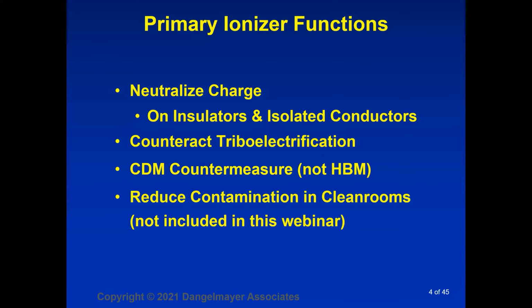Ionizers will also counteract triboelectrification. The ability to generate charge on materials in an ionized environment is lower than it would be if there was no ionization present. Remember that ionization is a CDM countermeasure. It's not for HBM. We don't use ionizers to neutralize the charge on people. It just wouldn't work. In any case, remember that it's almost always to solve a CDM related problem that we're using the ionization. And as I mentioned, it can reduce contamination in clean rooms.